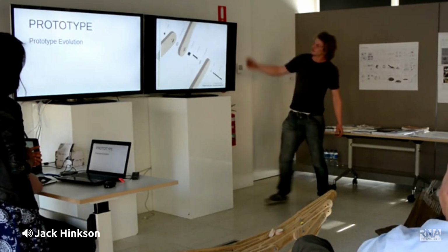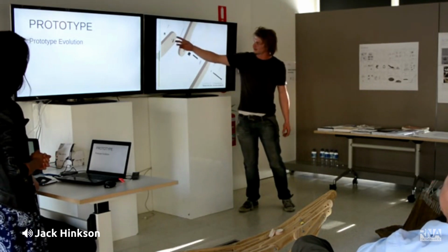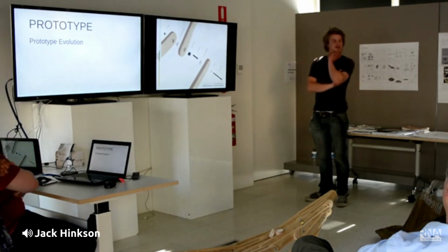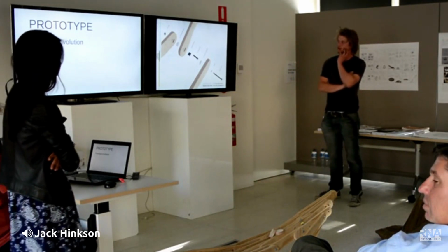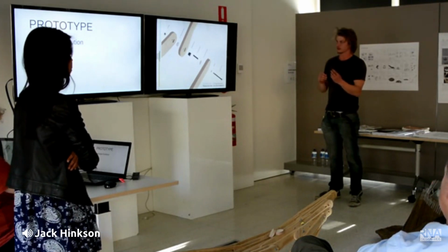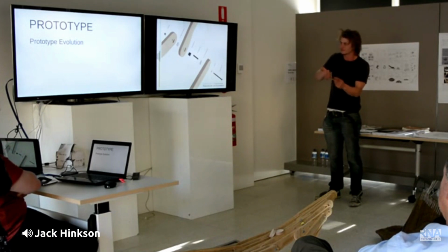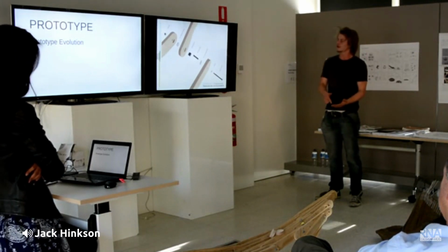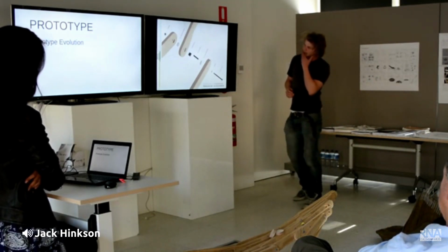We have, well, first of all, through our research, we came across T-nuts, and we thought that they would be a good solution for increasing the efficiency of our production. This enabled us to not have to stick our hands around and hold on to nuts and fiddle around and things like that. We could bang them into the back of it and then quickly just drive the bolt through to assemble it all.